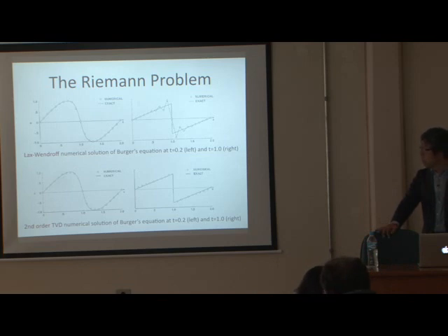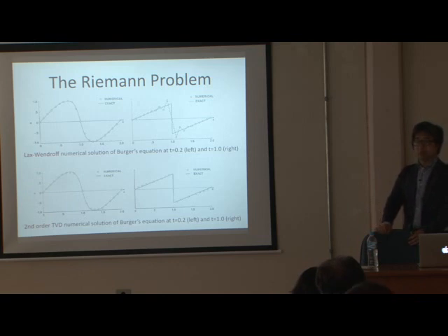Because this is a relaxation-based scheme or some other TVD scheme, it's usually solving the non-conservative form of the equation. It doesn't guarantee conservation of the energy of a simulation. Of course, we can get some estimate of how much energy is contained in the simulation and how much energy is going out. We can estimate how much conservation there is, but this is not guaranteed. So we are concerned about a more physically correct situation, and we think about the more conservative case there.